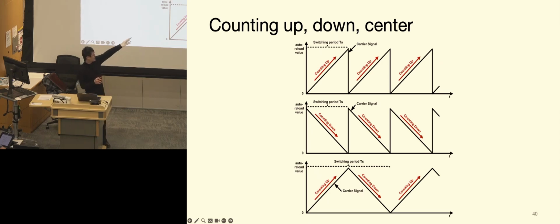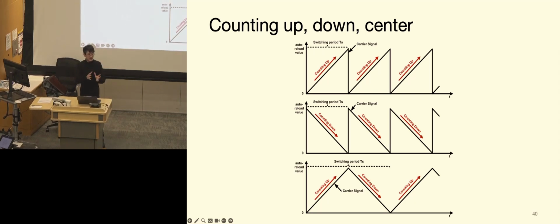The reason they have count up and down is that, say we have a 16-bit register for the counter and you run out of range, using this essentially doubles your counting range and gives you additional flexibility in controlling specific hardware. Just make sure you read the datasheet of whatever device you're interacting with, and map the signal, or the counter in this case, to the input range or performance range that it should have.